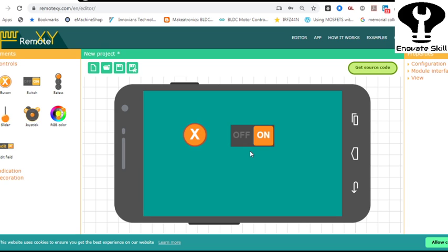So over here I'm just going to discuss for beginners, those who don't know anything about Bluetooth, and for advanced applications, those also will be able to program it and make it configurable. If you have the default Bluetooth module that I shared in the previous slide, by default you will find the Bluetooth name is HC05, the baud rate is 9600, and the Bluetooth password is 1234. If you want to make it according to your compatibility, you can do that also. You can change the name, password, whatever you want to change.